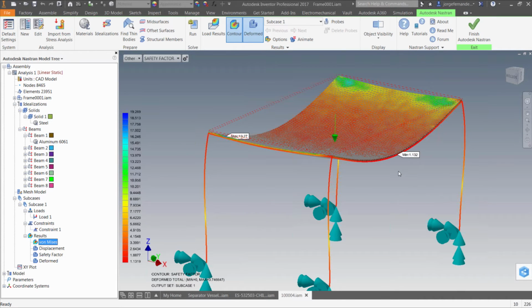You know, if it really was only 3 people at all times, then we're good to go. Why would I have over-engineered it going with the C6 channel, which is going to cost us more? It's going to be more shipping weight, right? And it's going to be easier on the forklift as well. I know the forklifts can carry a lot of weight, but come on, let's try and make this as easy as we can, guys. Let's not over-engineer too much. I would call that over-engineering myself.